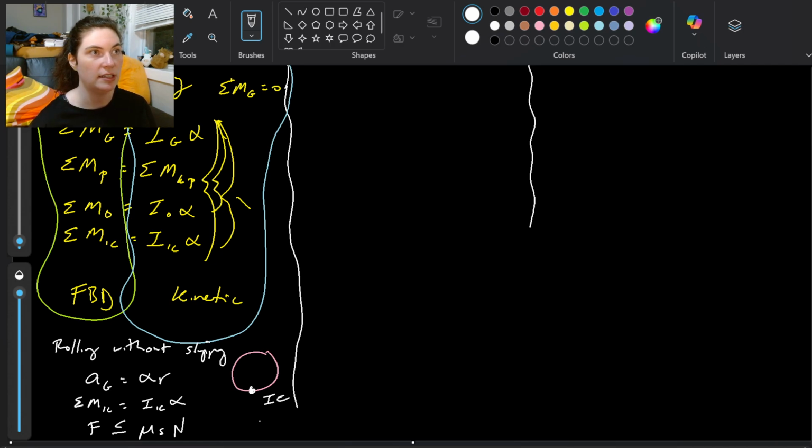If it becomes greater than that, that's when it starts slipping. So we can tell if there is slipping. Let me put it over here. If slipping, then the condition that we get is that F equals mu K times N. That's our coefficient of kinetic friction times the normal force, and they're just equal to each other. That's the case if it is slipping. And if it's not slipping, then it stays in that static territory and below.